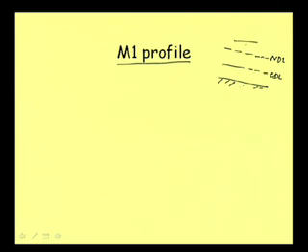I mean this one is M1 because the slope is mild, that is, normal depth is greater than critical depth, that is why it is mild slope, and the profile is lying in zone 1. So, this is M1 profile. Well, so what we are having by getting this sort of setup for M1 profile is that this is our normal depth Yn and this is critical depth Yc. So, one point is clear that the depth profile will be lying in zone 1, it means that depth at any point, suppose depth at any point in this profile is y.